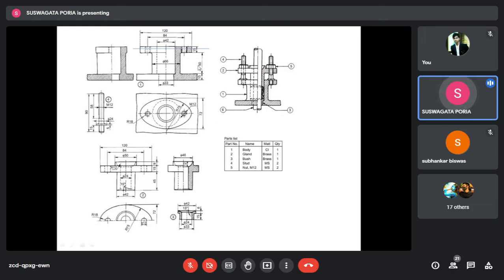First of all, in that case, I will suggest that you draw this half, because these total components are almost symmetrical. So this is the case where you will draw only one half, then you will mirror it. All the features on this side, you have to draw first with the stud and all those things. Then you will do the mirroring. Then the major component will be made.